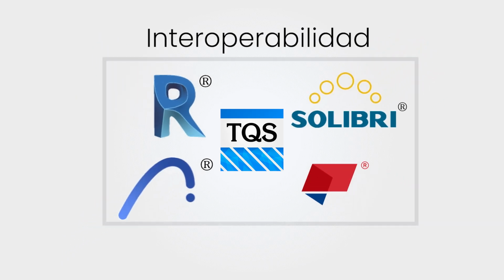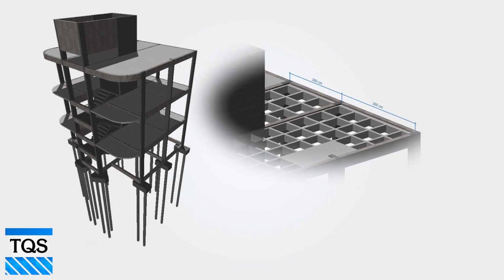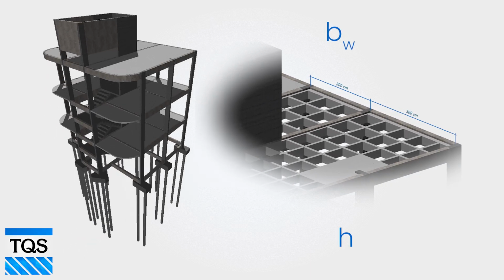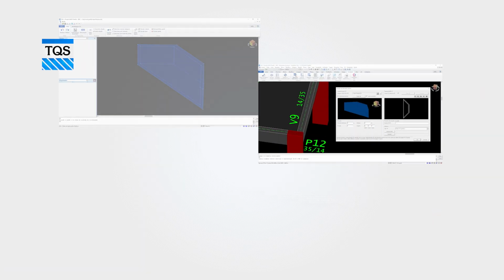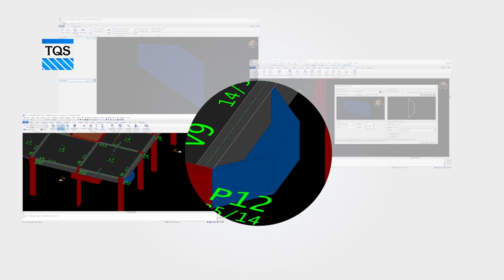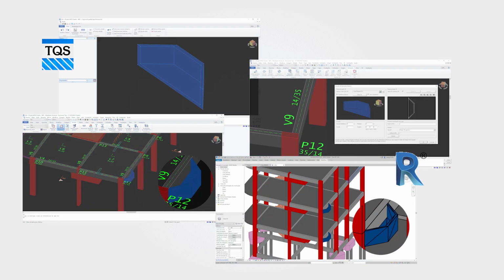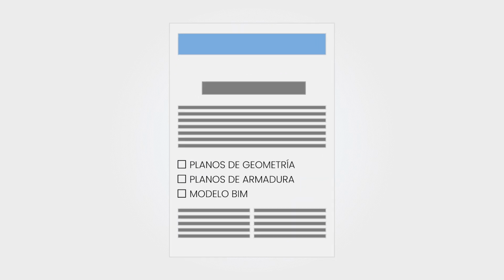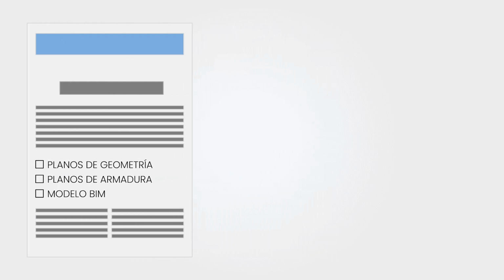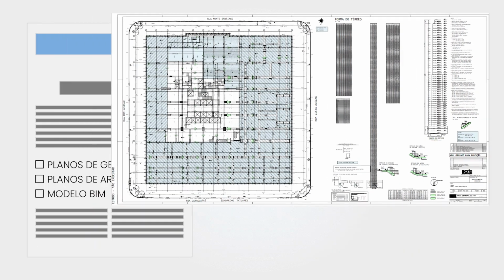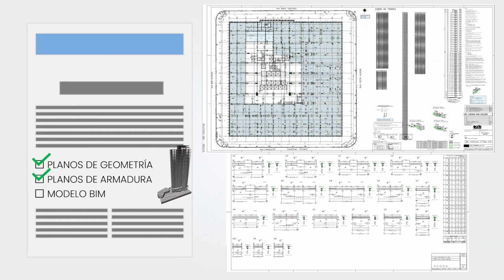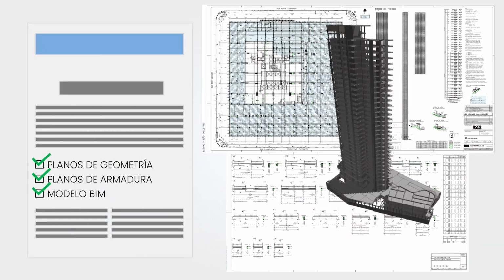best possible way. In the case of structures, the information that should usually be included in the BIM model is the structural elements, with their respective geometry and material. Both the main structural elements and those that are not part of structural integrity must be modeled. BIM is increasingly becoming mandatory by contract. In addition to the formwork and reinforcement drawings, the engineer is required to deliver a BIM model of the structure.